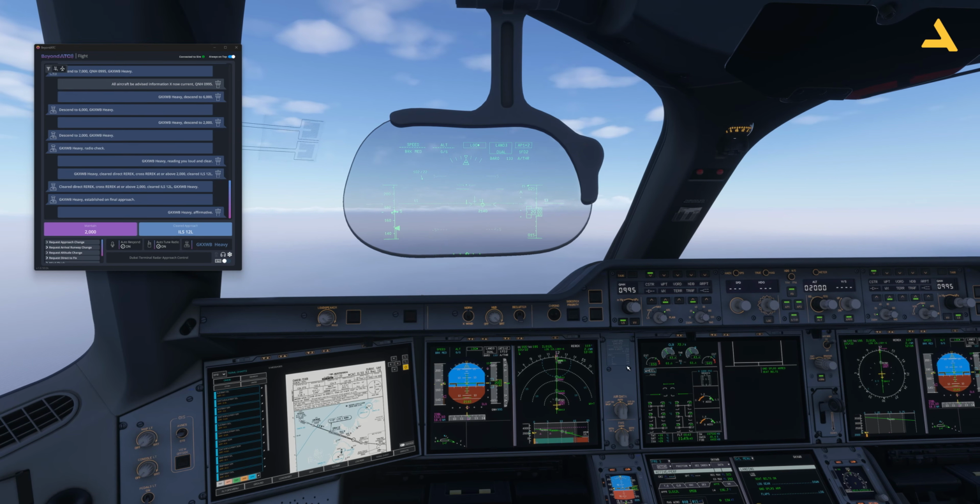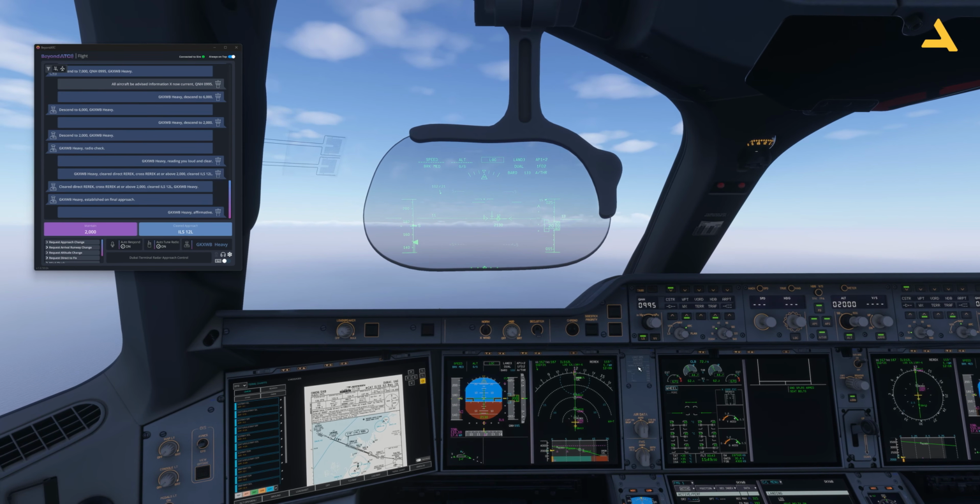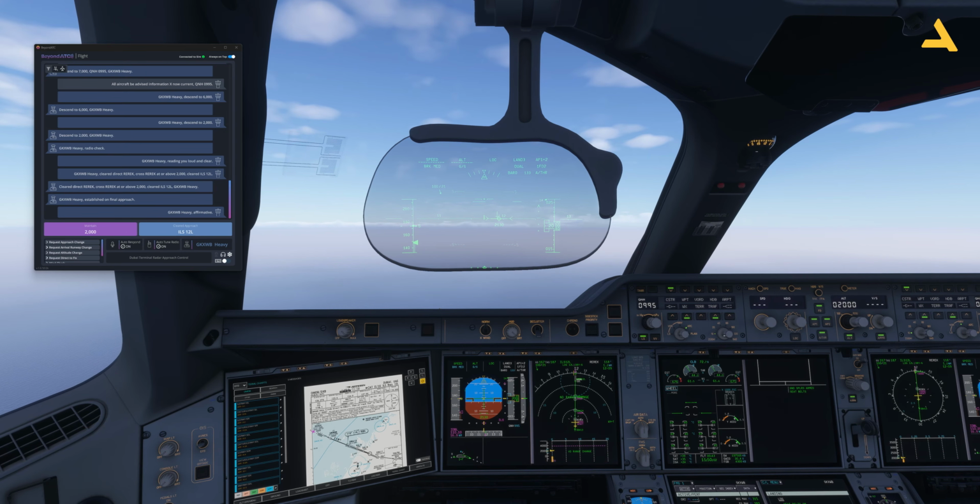Some heavy winds. I tried landing this plane before. It was a very bad landing, trust me. So I don't want to upload that video. So now I'm just trying to use the auto land feature. So everything is good now, and the flaps are set to position 1. Speed is below 185 knots.